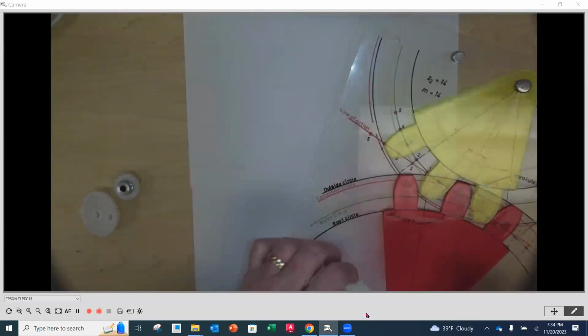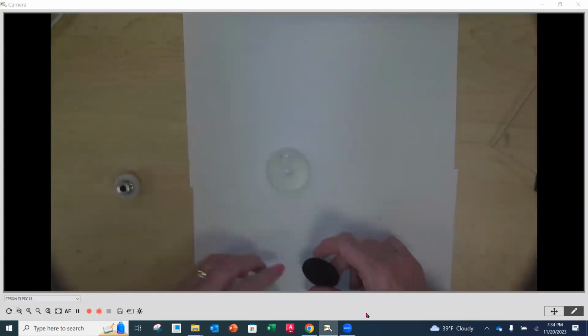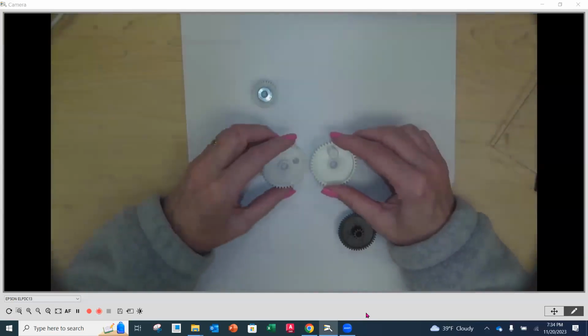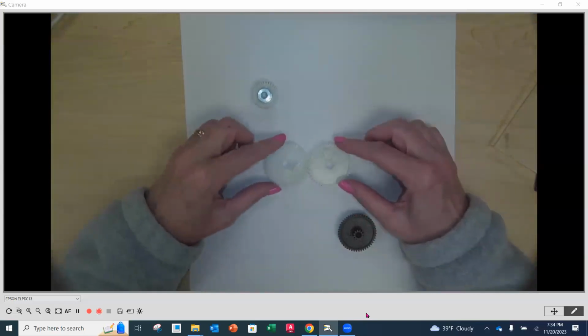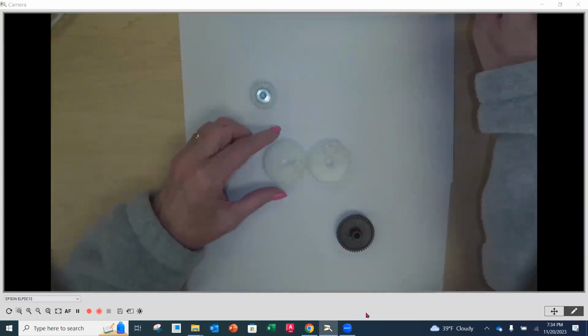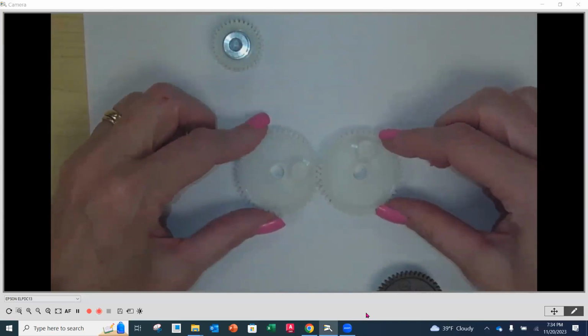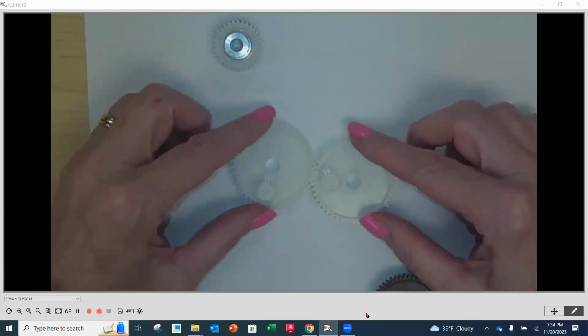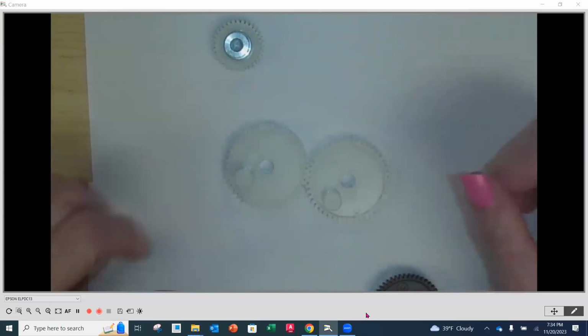Unfortunately, online, you won't be able to get the same experience, but when I look here, I've got these two gears, zoom in here. You're going to notice, and I know it only can go by sight here, but these move very freely with one another because they have the same size tooth. They have the same diametral pitch, okay?